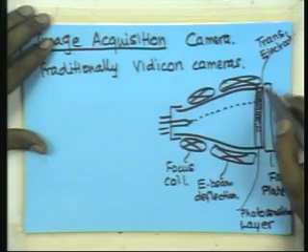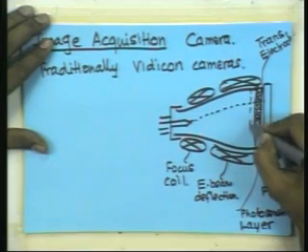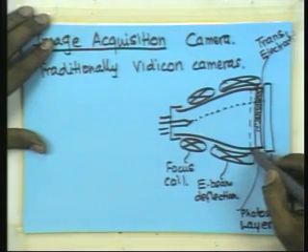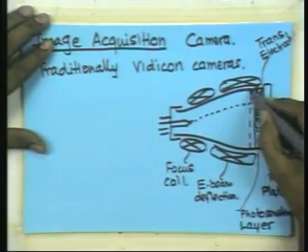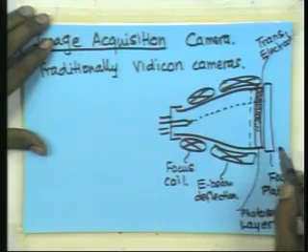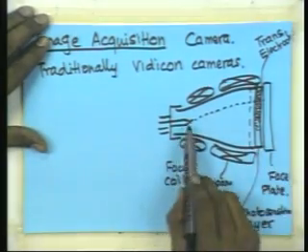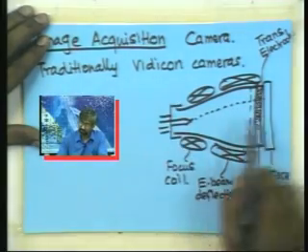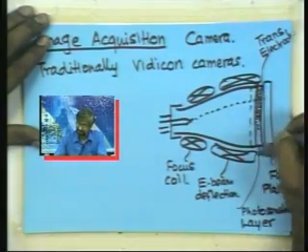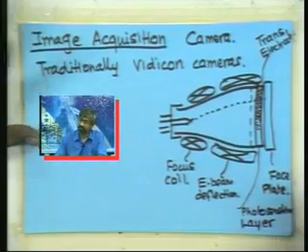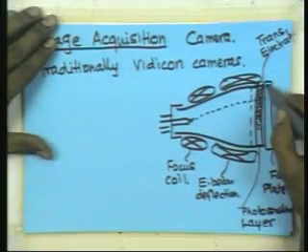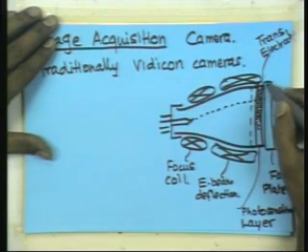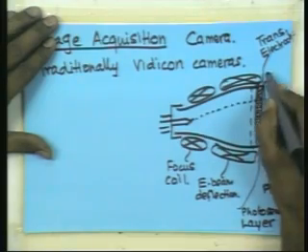Okay. Next to that, we have a fine grid of another electrode which is connected to positive charge. Okay, I am sorry, it is connected to negative charge. So, basically the idea is that we are going to slow down the electrons by using this grid, so that the electrons strike the back of this photosensitive layer with very low velocity. Okay. What we will do is this transparent electrode will be assigned a positive charge. So, we assign positive charge here.